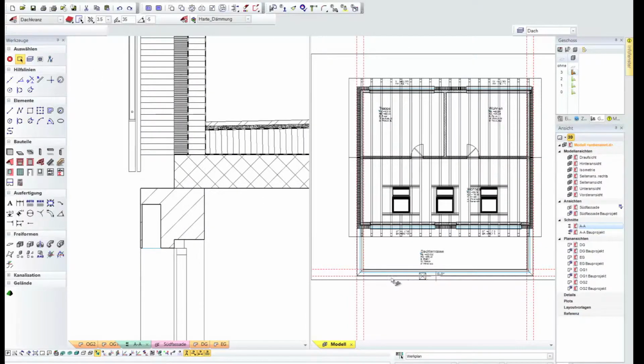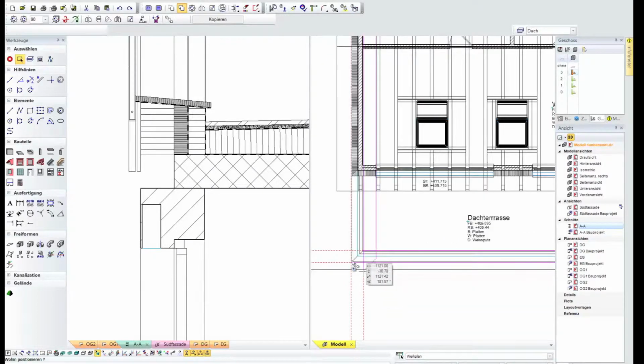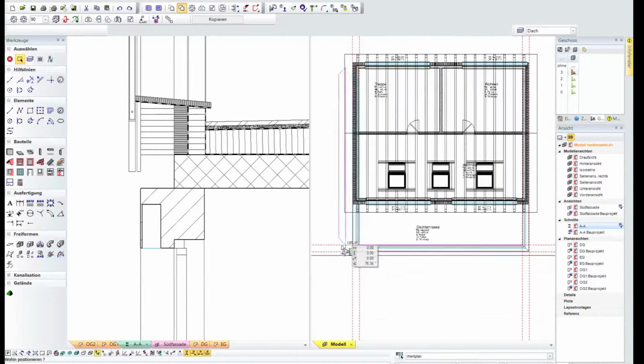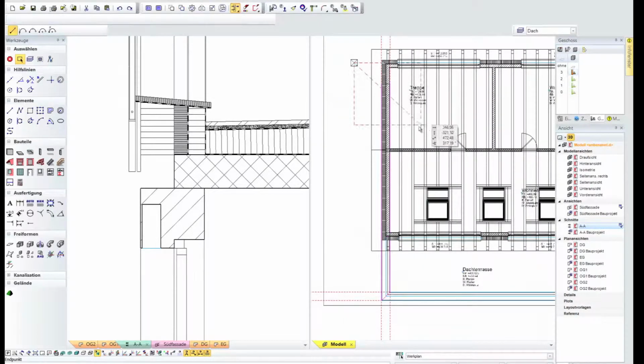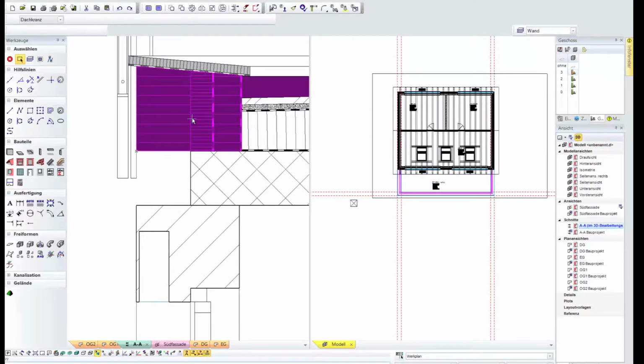I now enter 2 points for height and incline, and immediately the roof edge is displayed. Note also how the different layers intersect each other in a logically consistent way. This construction will now also be applied to the lateral parts. I set limits for these, and the information is now also displayed correctly for the side parts.